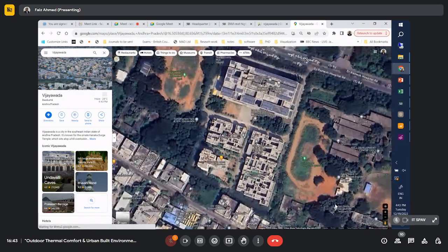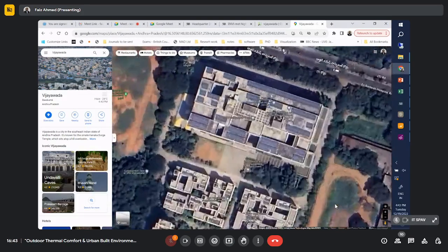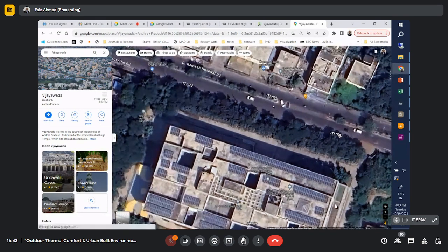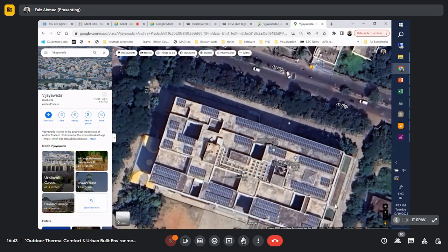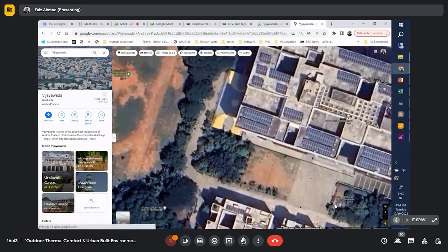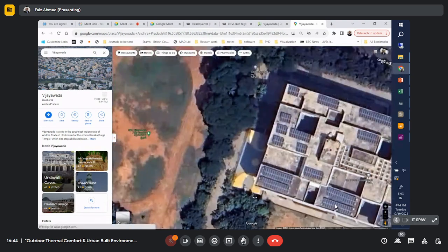What you can do is prepare a base map for this entire campus. To start with, create maybe 3-4 layers only. Maybe the major road. Second, the concrete pavements. Third type of layer, we have some greenery and then pavers. So you can have three types of soil finishes. And then we have vegetation.